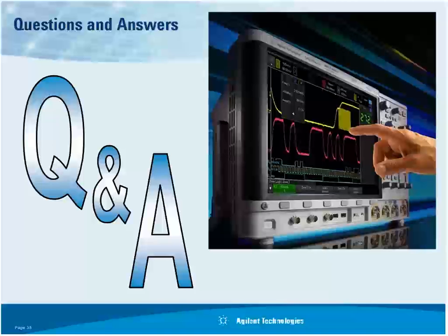Now, getting on to the current waveform going through the drain and source of your transistor, you're going to have to lift the leg or cut a trace and create a wire loop in order to get the clamp-on probe around that. Now, for the power supply measurements I made as a demonstration board, we actually laid out the PC board to create a loop, but you're not going to do that on your end product of your power supply. So you're going to have to do some modifications to do that.